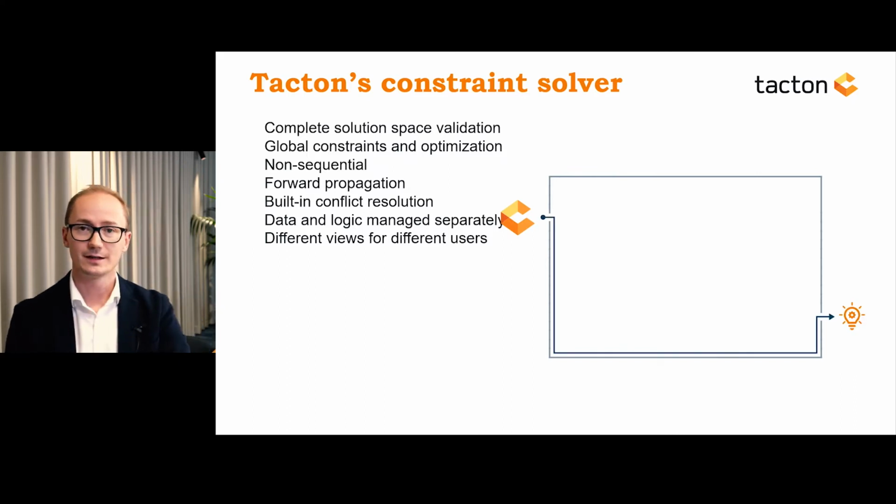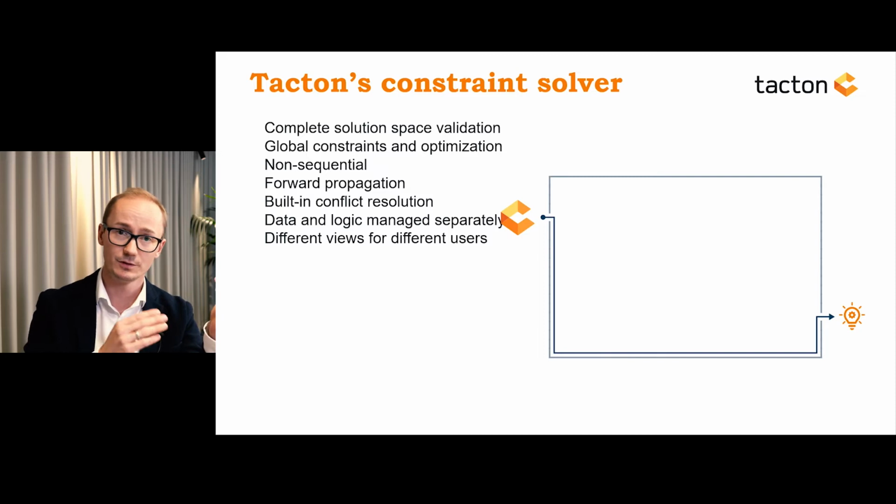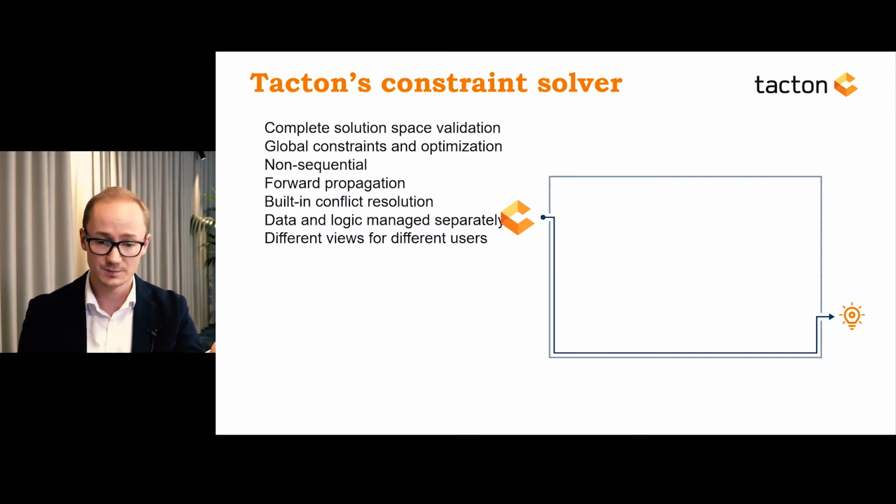The first thing that the Tacton configurator will do before we put in any constraints, if it wants to find a solution, it will be very lazy. It will go into the list of available components, and then it will just say, I'll take the smallest one in each of the tables, the first one I find, with the smallest diameter. So if you take the wheels and tires example, by default it will be lazy. If you don't select anything, it will take the smallest rim and the smallest tire and see if they fit together. And if they fit together, it will be happy and feel that now I found a solution.